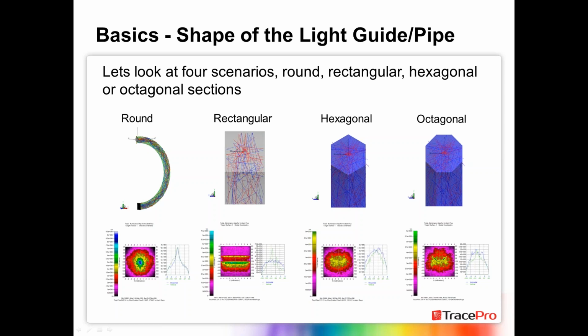Oh, that's correct. Yeah, that's one of the things. If you're trying to get an SP1 type finish out of a 3D printed light pipe, you're not going to get it. But what you are going to see is that you should be within a factor of 2 ballpark in terms of efficiency. The angular output should look pretty good, except if you have a lot of exit areas. If you have light where you have 90-degree bends, the rougher that particular surface is, the more light you're going to have leaking out of the pipe. And it's going to leak all the way along.